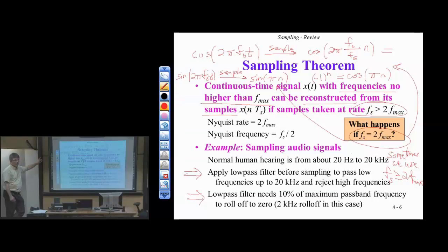Now, why 44.1? We talked about this already, but what you could record in 1982 at that rate was pretty limited. If you use a TV format called PAL or NTSC and you stored 3 audio samples per row of video in each frame, you get a 44.1 kilohertz sampling rate.